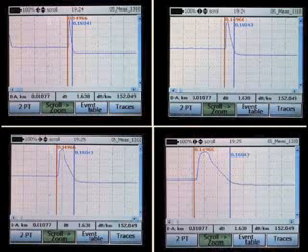There's also a 12 nanosecond pulse in the upper right-hand corner, and the 6 nanosecond pulse in the upper left-hand corner we chose for our test. By choosing the appropriate pulse width, you can get the best resolution and distance trade-offs on every trace. But you need to know how long the cable plant is and how the OTDR trace will be affected by the pulse width in order to make the right choice.